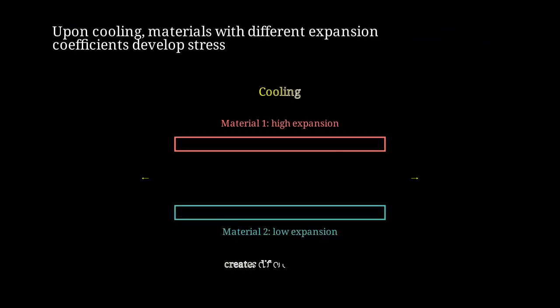Here's a visualization. Upon cooling, the top material wants to shrink more than the bottom material, but they're bonded together. This creates compressive stress in the top layer and tensile stress in the bottom layer.